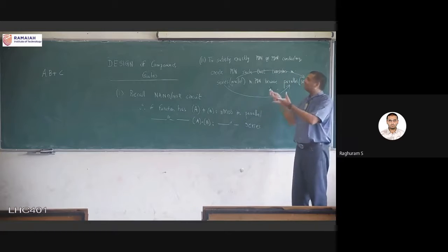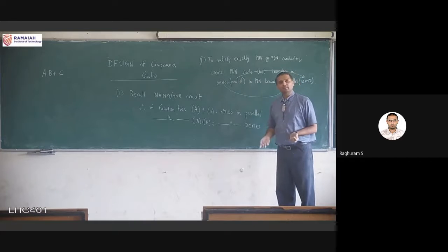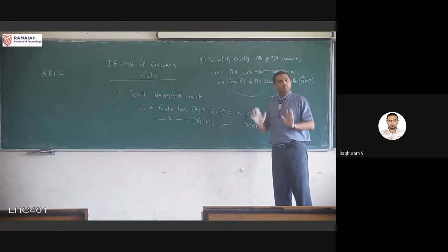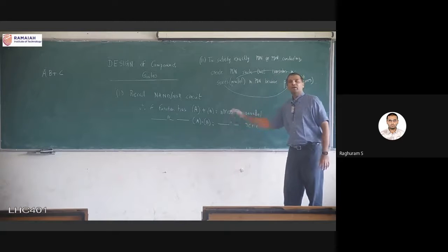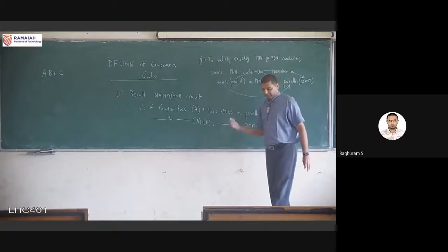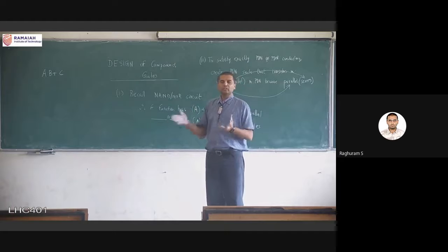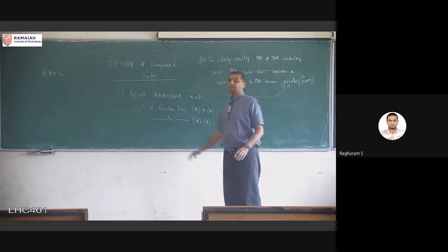And obviously this is the pull up network, so all these transistors are what type? They have to be PMOS transistors. The pull up network automatically uses PMOS transistors, so no NMOS transistor confusion at all. Every NMOS connection we have to see and create the opposite. And the reason why this works is basically that this all goes back to De Morgan's law. De Morgan's law says that A plus B the whole bar equals A bar times B bar. So here also the same thing will work. The explanation is there in the book, but this is the procedure.